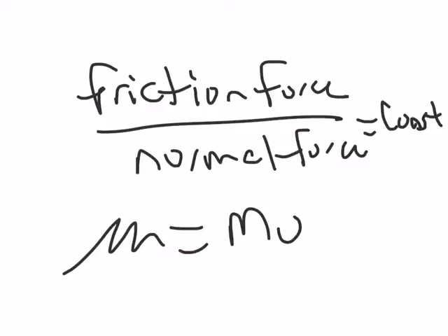You can see it would be roughly 7% in heavy rain for friction. So coefficient of friction is reduced and braking distance is increased. So if too much brake pressure is applied, the brakes will lock and the wheels will stop rotating. And this happens as the tires skid and rubber is melted and separates from the tread. Besides the possibility of causing a blowout, the coefficient of friction is reduced and braking distance is increased.